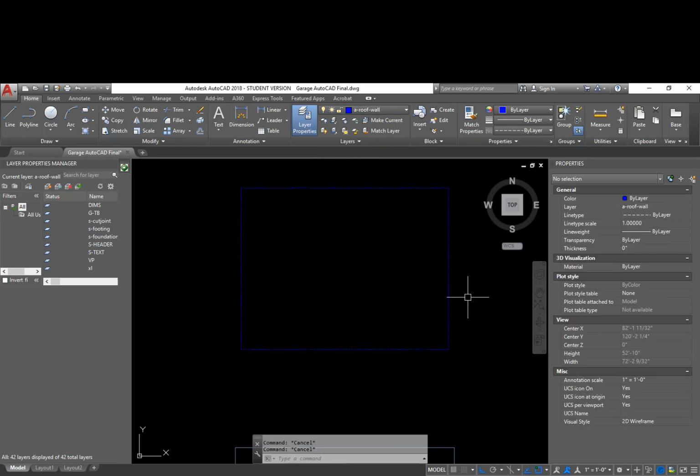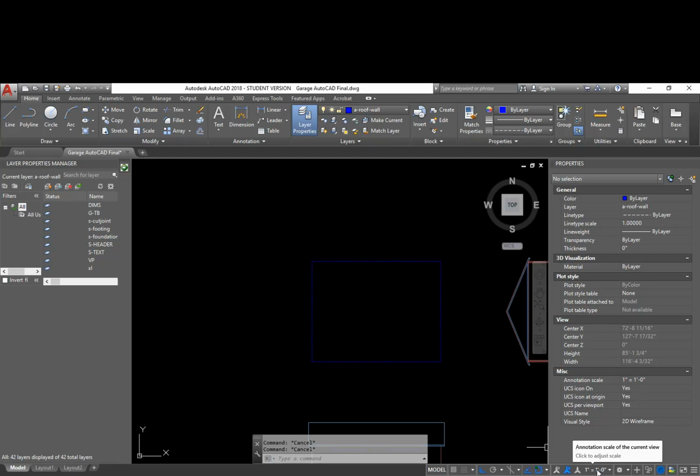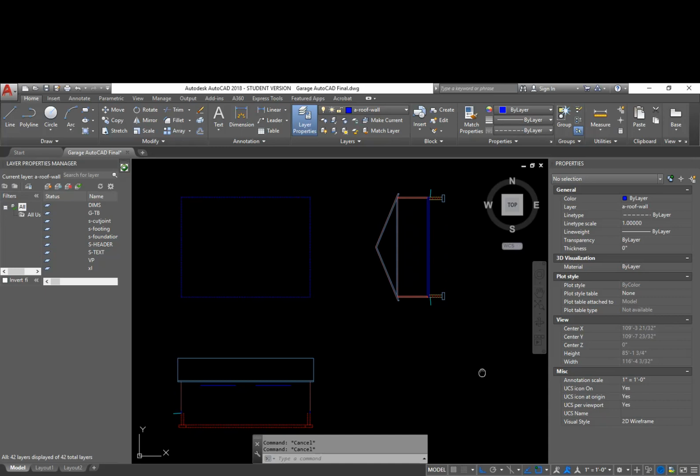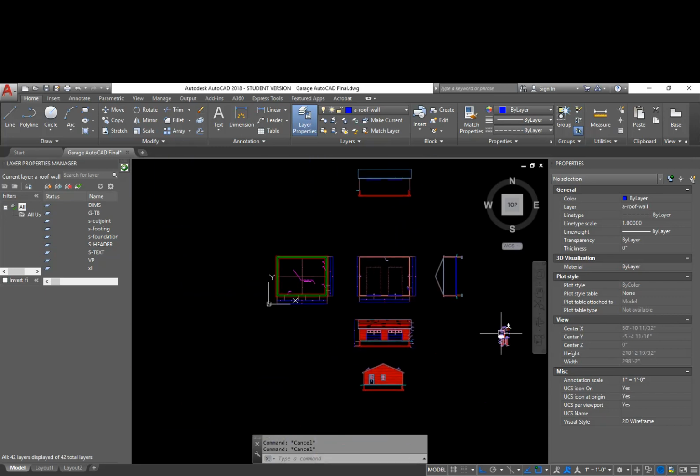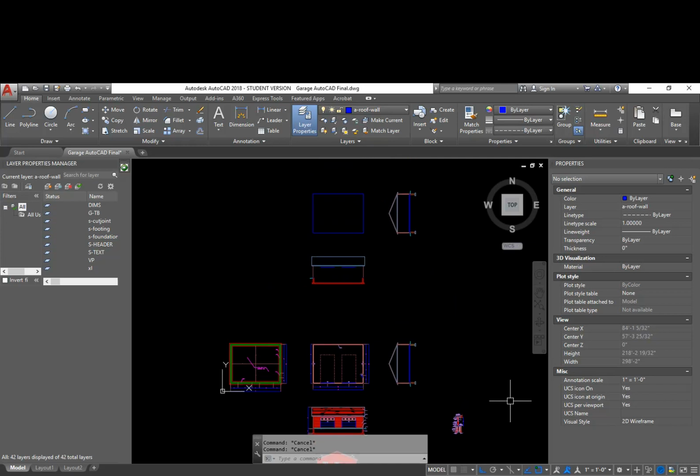All right, so the first thing that we need to notice is these hidden lines look really, really small, and the reason for that is the last time I was working on this drawing, the scale was at 1 inch equals a foot for my typical wall section. So my instinct is to go through and change the scale of this to 1/4 inch equals a foot to match the other floor plans.